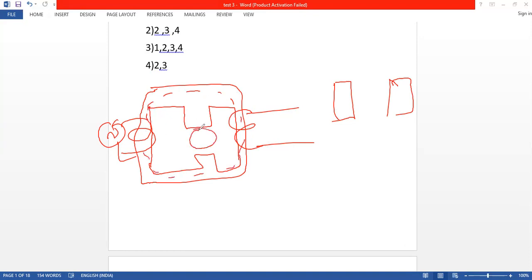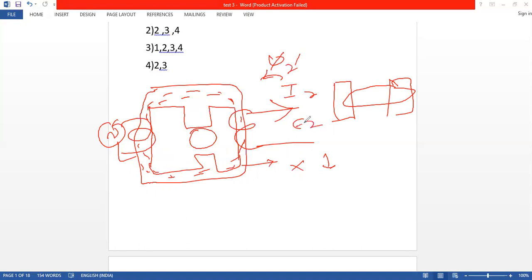See here, reluctance is more, so most of the flux will pass through this part. Okay, so leakage flux is less, X is less. When you short circuit these two metals, then current will flow. This current will create phi 2 dash. So there is an opposition of E2. So now most of the flux faces opposition.